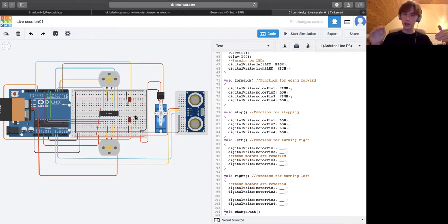However, as we're only using 2 motors and not 4, we have to think, how are we going to turn left or right? For example, our motors are spinning in this upper direction, and I want to turn in that direction. Basically, I have to keep spinning this motor up while I change the direction of the other motor. As this motor is going up and this motor is going down, the robot is going to turn in that direction.